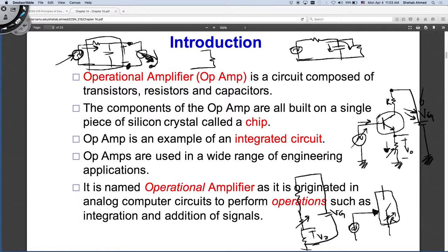You, transistor block, I want you to look like a variable resistor. The value of current, the 4 to 20 milliamp in your flow meter measurement, or the 1 to 5 volts in another sensor, is going to determine the value of this variable resistance R. So I created an output voltage here that is controlled by my input signal, which is my sensor output. But the power to run this, or to supply this resistor with current, is not coming from my sensor.